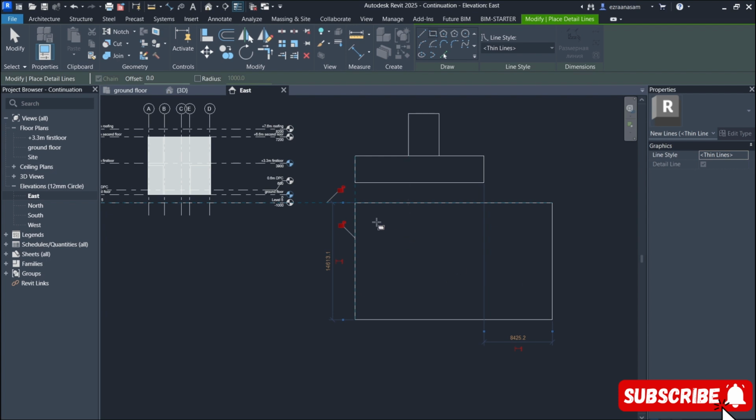So if your building is like this, the foundation is laid completely under the ground, and any element comes out from the foundation. Sometimes a slab foundation is not economical because you have to spend a lot of money, but it is good to use when you are constructing a building that has many floors, for example 10 or 12 floors. The load from such a building is huge, so it's good to invest in your foundation.